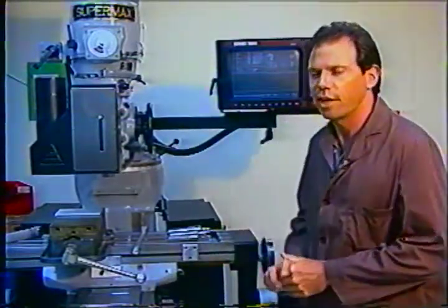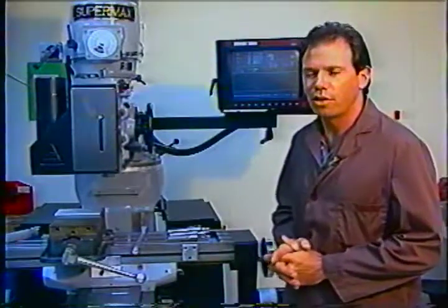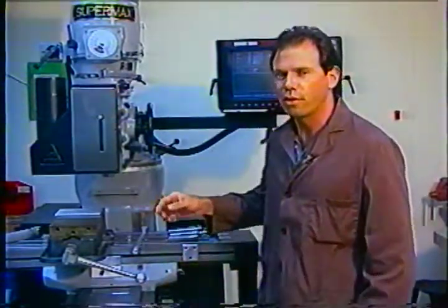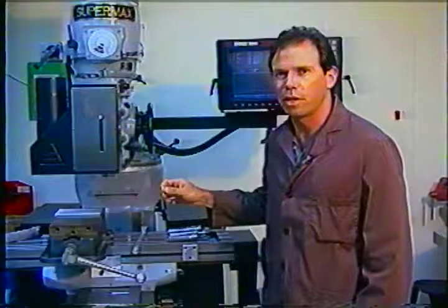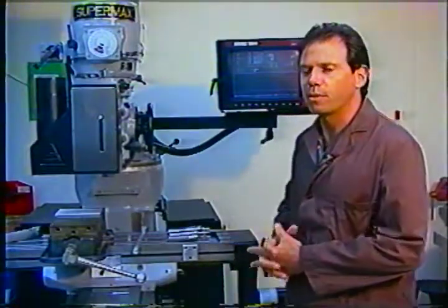Now that we've finished programming the workpiece and checking it in draw graphics, we're going to move on to the two setup steps involved in setting up this workpiece. First of all, we have to set absolute zero, in other words, X0, Y0, where all our dimensions were taken from on the blueprint. We decided we were going to set that up here in the upper left corner of the workpiece that we're holding in the vise. The second setup step will involve doing the tool length offsets.